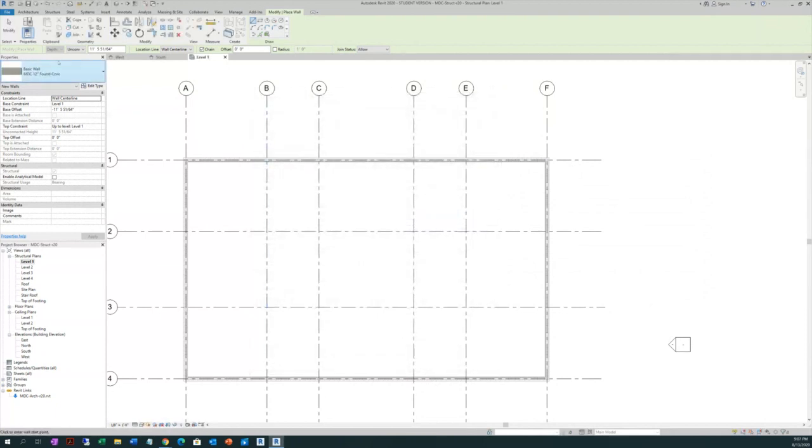Now, over here, you see, you are on level 1. You are going down to the top of the footing, correct? So that's the depth, because when you are doing framing, Revit is going to always put you on the depth. So you have to be aware that sometimes you are going to place some columns, and the columns are going from level 1 to level 2, but then Revit may think that it's going down, you know, it's framing, because a pilaster could be a column.